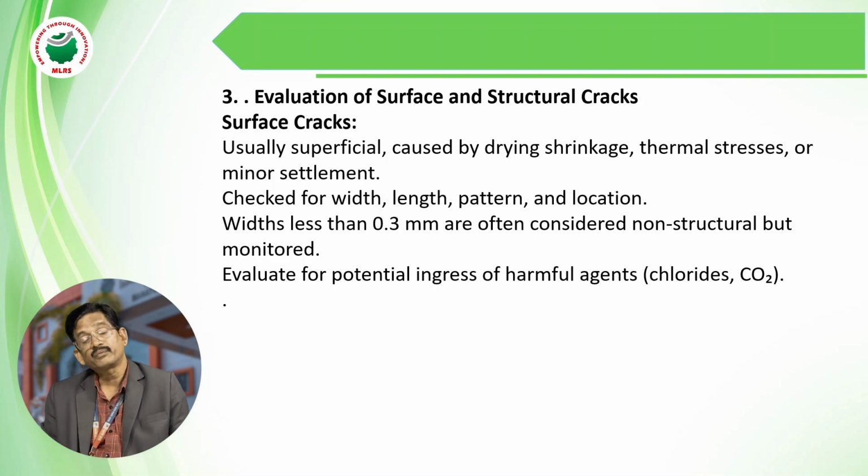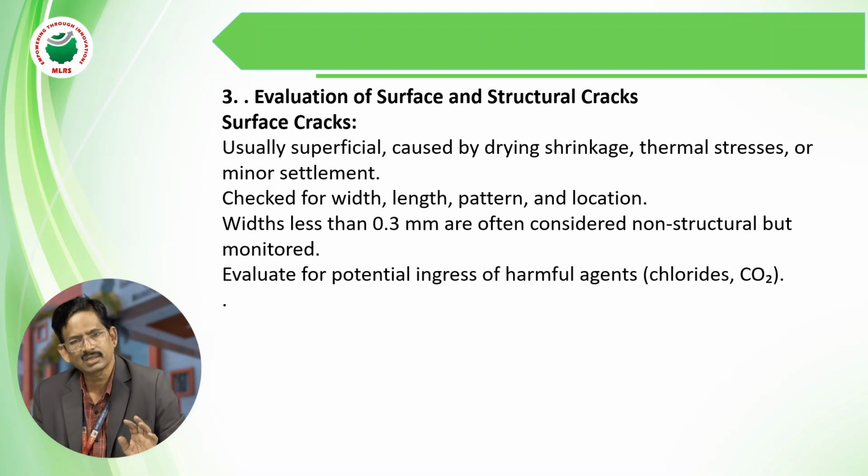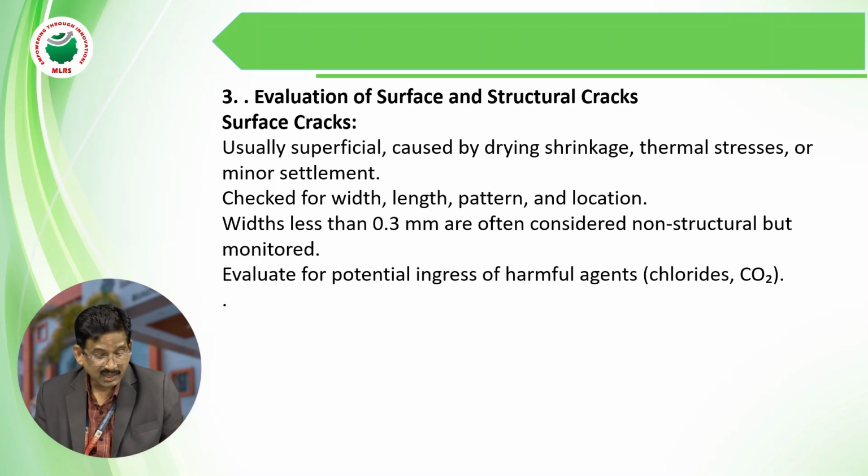Evolution of the surface and structural cracks. Surface cracks. Usually, surface cracks are caused by drying shrinkage, thermal stresses or minor settlements. Already we know what drying shrinkage is. Because of the temperature variations, we are getting some cracks. These cracks are called drying shrinkage cracks.